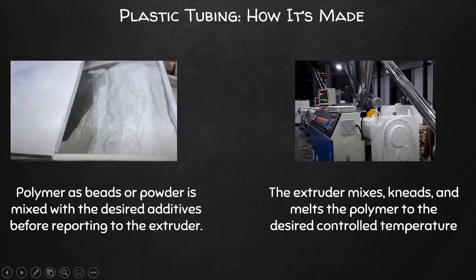Right. Let's talk about plastic. The fabrication of plastic tubes is similar, only in the initial phase of the process compared to steel pipes. The plastic material usually comes in the form of beads or powder. So if I were to buy high-density polyethylene from Sasol, from the wax section, I would get the bag sent to me, maybe 25 kilo or 50 kilogram bags. And the bags would contain these little beads. I think they're like 1 or 2 millimeters in diameter.